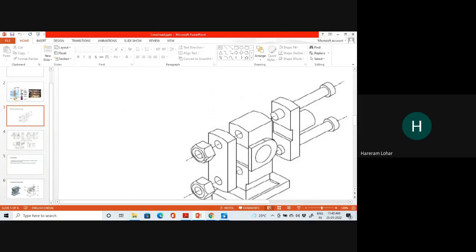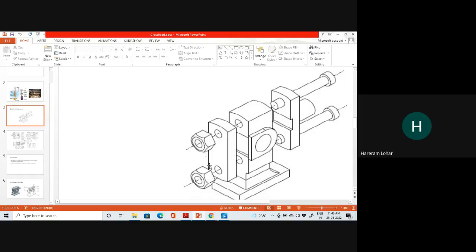But the nut will be the hexagonal nut. Here we can clearly see the chamfering on the nut. Generally, it will be chamfered by 30° or something. There are empirical formulas to represent the chamfering dimensions, all those things. But the cross section of the bolt head is circular, while the nut will be the hexagonal nut.